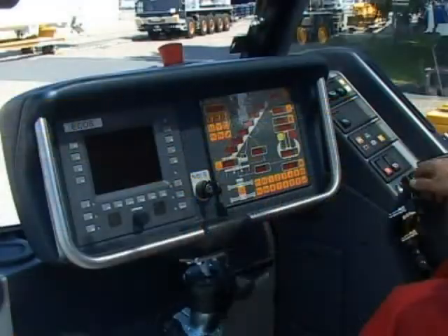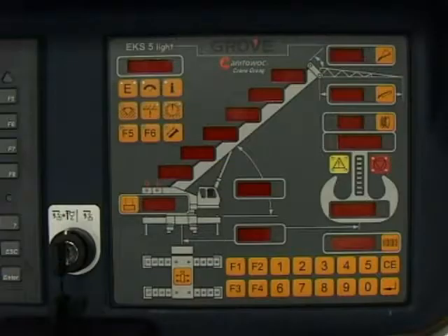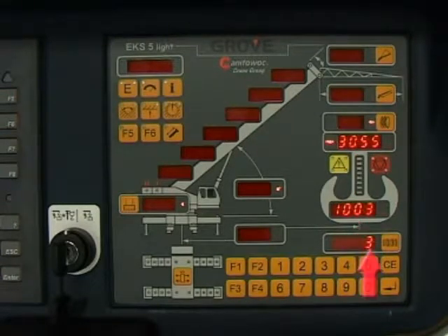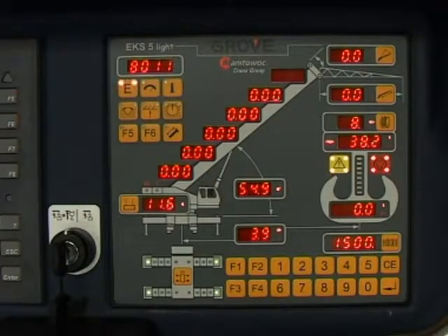are calculated. On system start via the ignition switch, a self-test program will run to test the RCI component. You will then see the crane model, software version, and version step shown on the display. The display will then configure automatically depending on the expired time since it was last used. If less than 48 hours, the last entered reeving and RCI operating codes are loaded as shown.